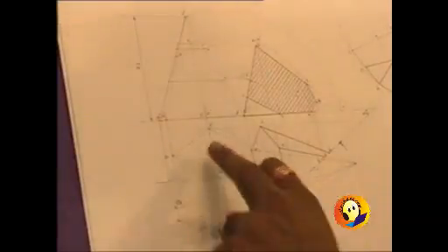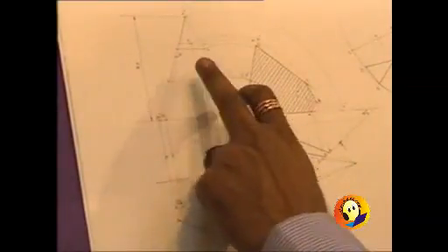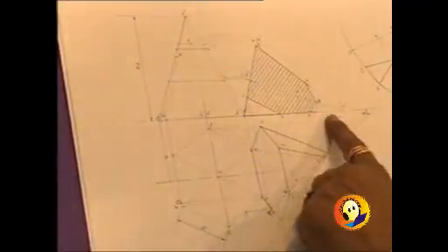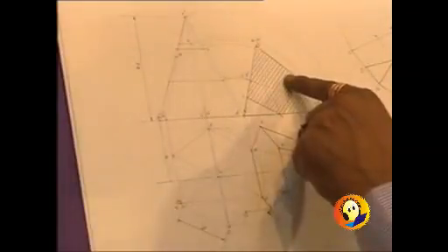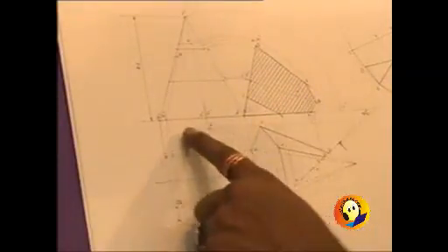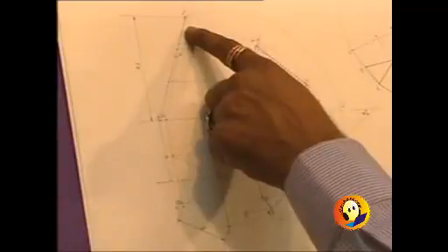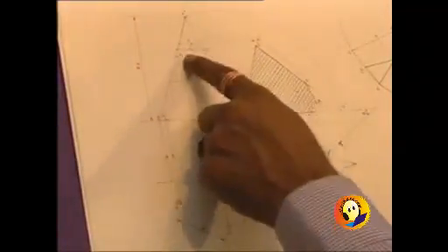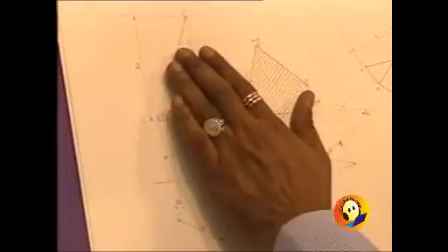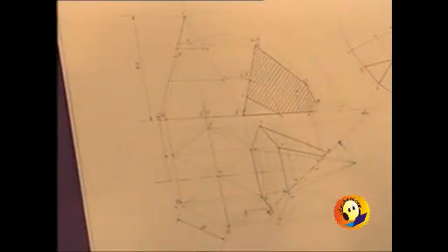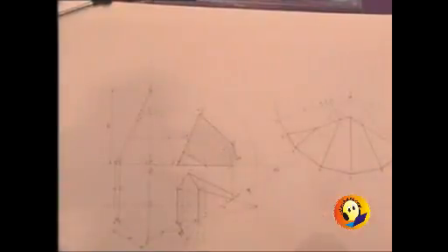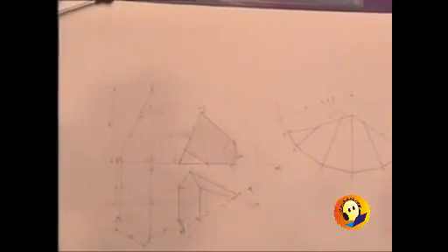First we had started with the hexagon, then completed the front view. It was resting on a triangular face, so it was rotated, then cut by AVP. Then we have completed the sectional view. Then we have obtained the true length of one of the generators, and these points are to be transferred. So I am as if taking it back to the normal position, transferring the points to the elevation and completing it. So a clean view of this particular figure.